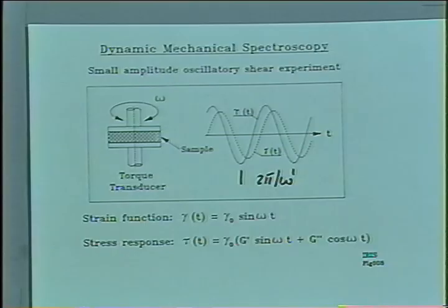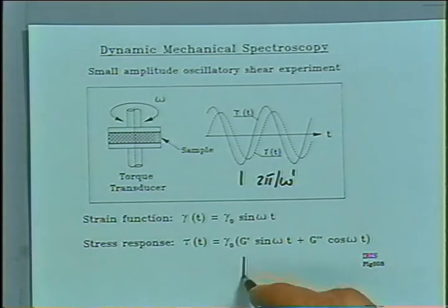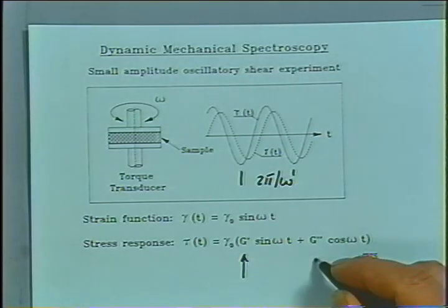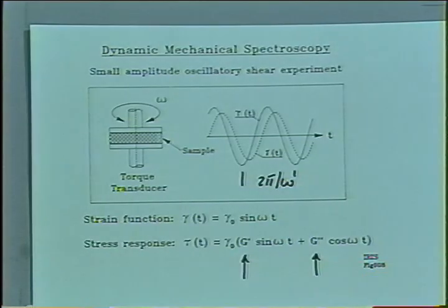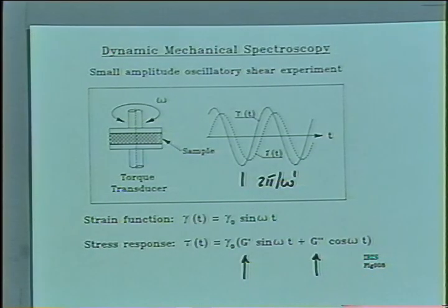The third advantage really is that we are probing the material with G prime and G double prime. G prime contains the spectrum by itself, and G double prime also. Both give a complete description of the relaxation modulus, but they're probing the modulus in different ways. And by combining those two functions, we have an easy time evaluating our spectrum.